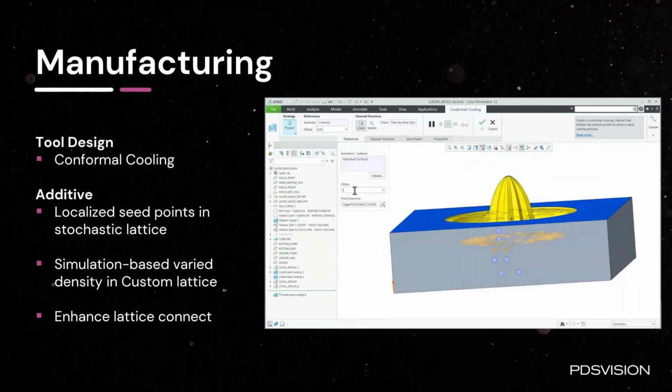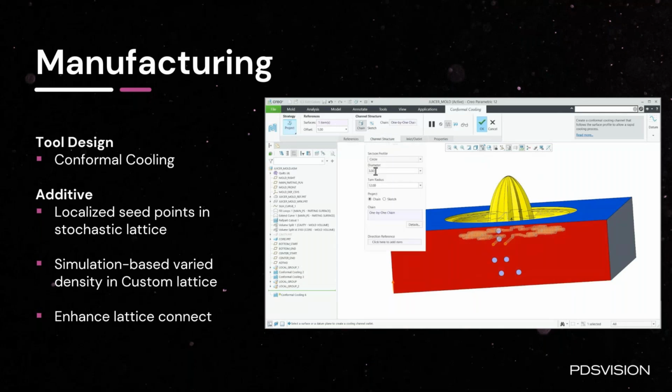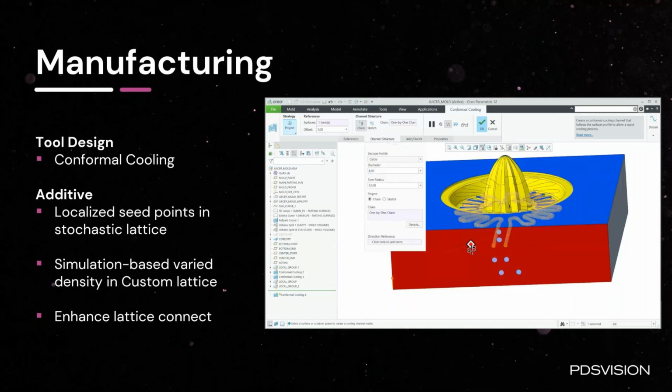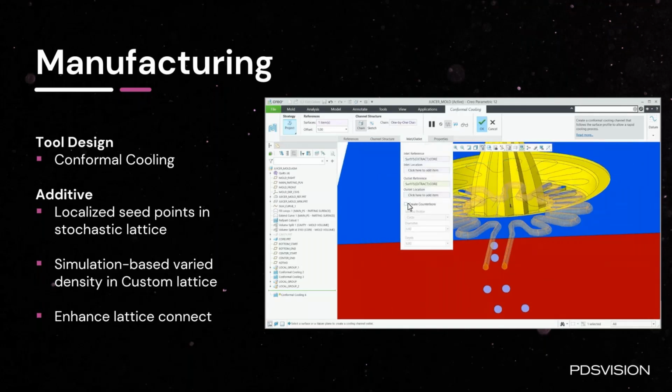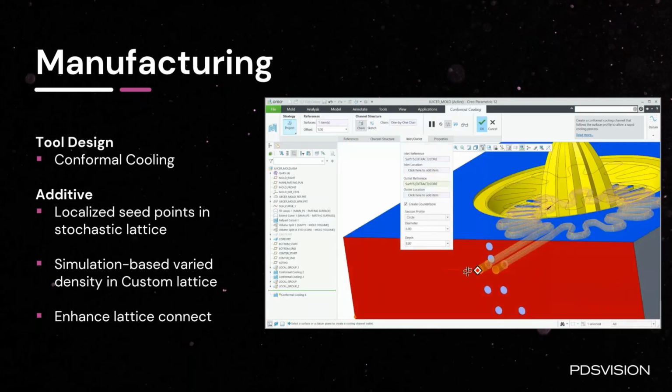That leads to more even cooling in the mold, resulting in faster production times and increased tool life, these sorts of things. These channels are typically produced via additive manufacturing and have control over the shape and the channel to help in the printing process. Okay, so you can modify these things.